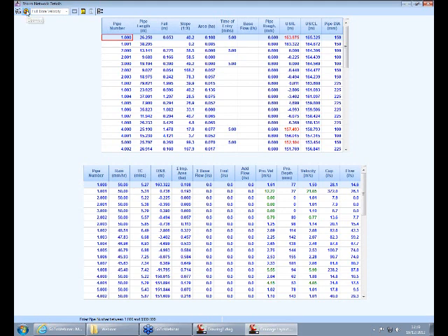Instead, we can use the Optimize engine. We can click yes on there. So go Optimize and click yes, and now the levels have updated. Instead of being down at 0, they're now up to more sensible levels. They should still achieve self-cleansing velocities, minimum cover, and adequate capacity for the pipe diameters to take the flow. Currently, you see we're not achieving the proportional velocity on these pipes. That's because we have no areas assigned to them right now.